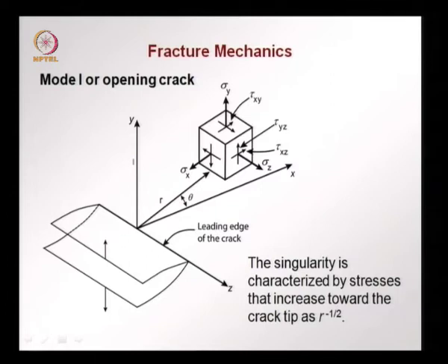What we can imagine is, now we have a crack, a sharp crack, and let us see what happens in front of this crack. So, the crack is advancing this way, and if we look at the stress state of a point ahead of the crack tip defined by this distance from the crack tip r and an angle theta, we would find that the stresses become infinite as we approach the crack tip, and this increase in stress is defined by the factor r to the power of minus 1/2.